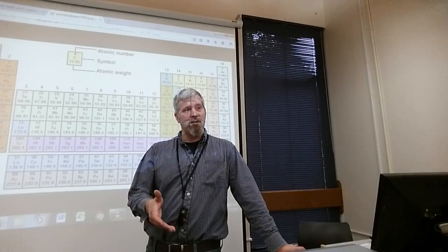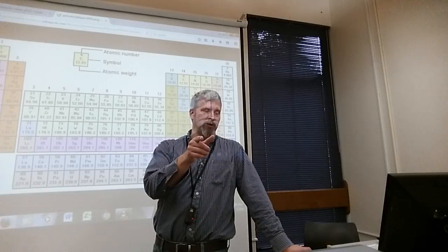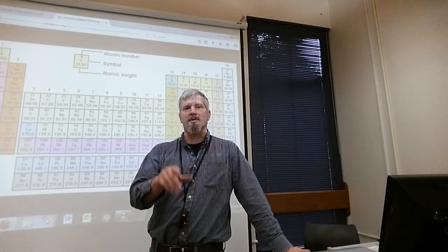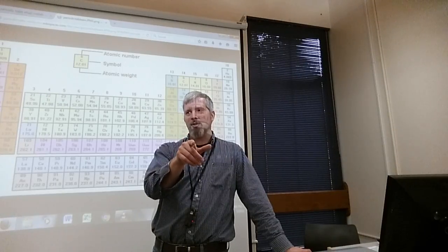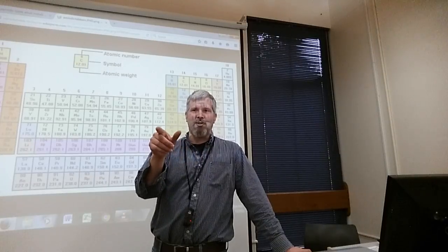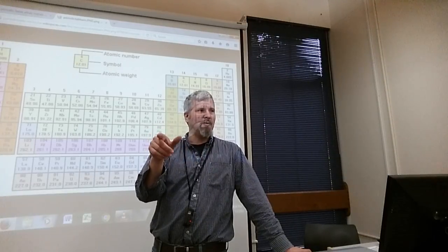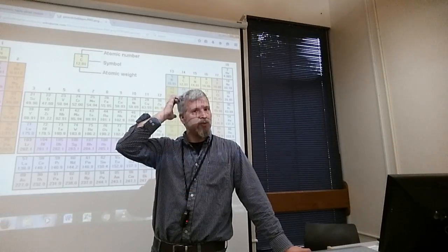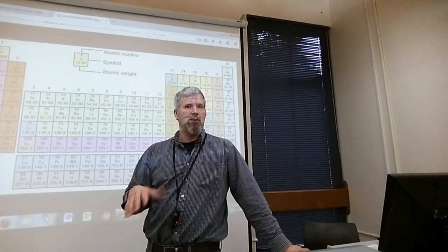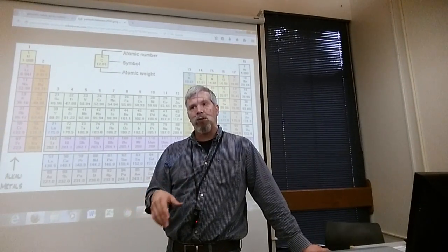And then we can find out what is the optimal solar concentrator, and then we can try to figure out ways to cool them. One of the ways we were kicking around is with the small one especially. The big one, we could manufacture something, but the small one is roughly the size of an old Pentium 4 processor. So what we could do is take the heat sink off of the back of a Pentium 4 processor and stick that on the back of that thing and heat up the front, and then we have this big active cooling fan on the back to keep the heat down. We can concentrate these PV panels and get more energy out as long as we keep the heat down. If we don't, it degrades them a lot faster, and the life of them goes down really quickly.